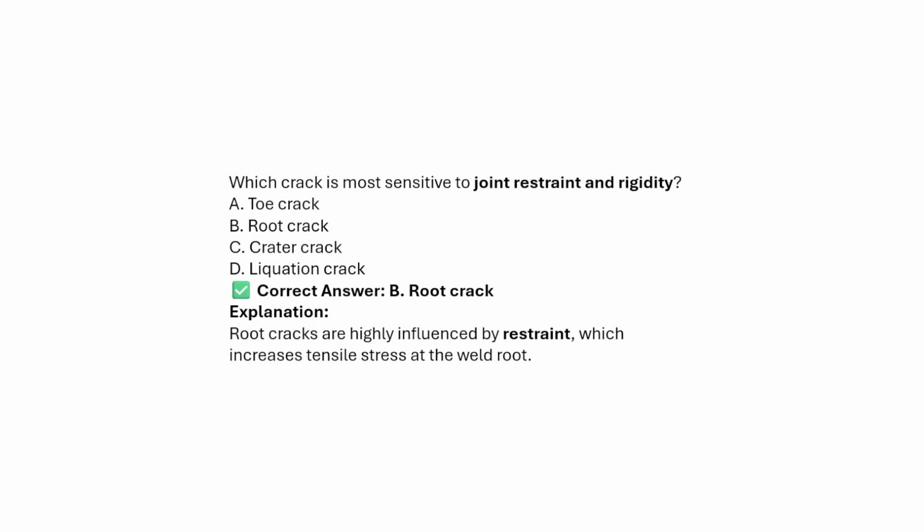Next, which crack is the most sensitive to joint resistance and rigidity? Toe cracking, root cracking, crater cracking, or liquation cracking? The answer is root cracking. Root cracks are highly influenced by restraint. Restraint is nothing but clamping of the workpiece, which increases the tensile stress at the weld root.